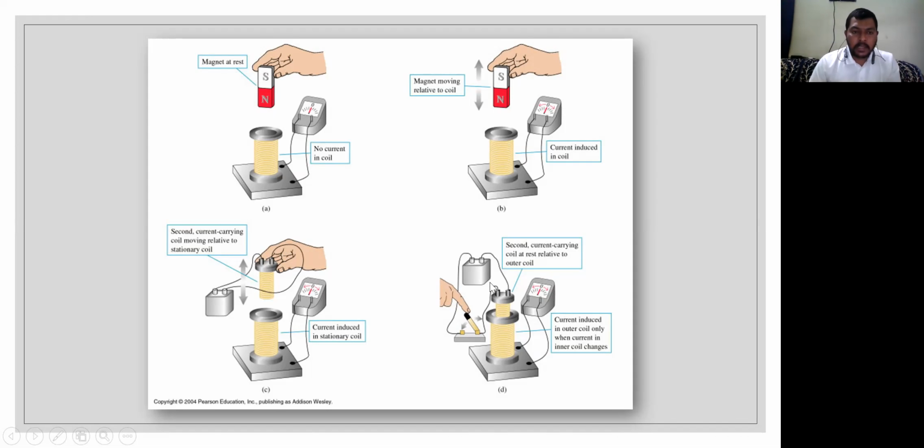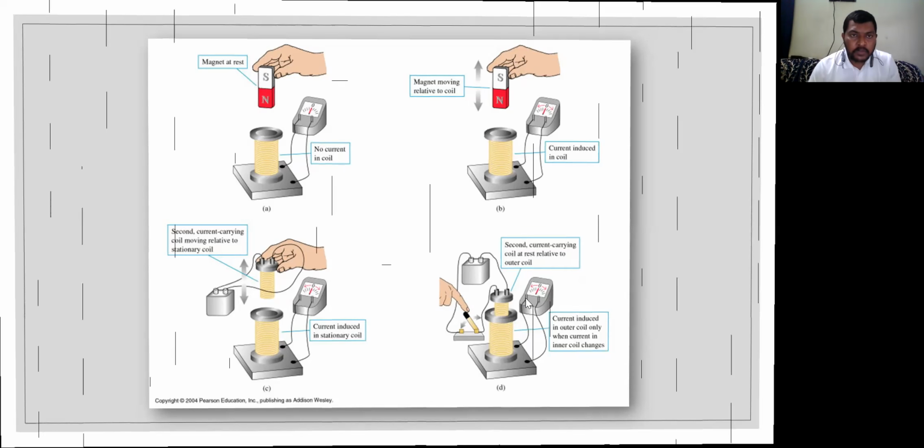As you are able to see, you can measure the displacement or distance. Small distances can be measured by using this coil. Distance is another physical parameter which we expect to change, and depending on the voltage which is induced in this coil, we can calibrate it to the displacement, right? So this is the electromagnetic principle.